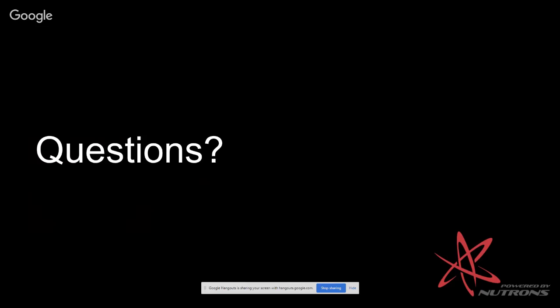If you have older robots that are just chilling in a corner somewhere, I'm not sure if you take them apart after every year, you could use those. That can be useful for having a ready amount of code and then tuning when you get the real robot. A lot of times, going through the motions of tuning, getting all your auto driving right on the practice robot, makes it a lot easier once you get it to the real bot. Even if it's just the drive phase, if you spend all that time figuring out your motion profiles and which way all the signs go, it'll be a lot easier once you transfer to the real robot.